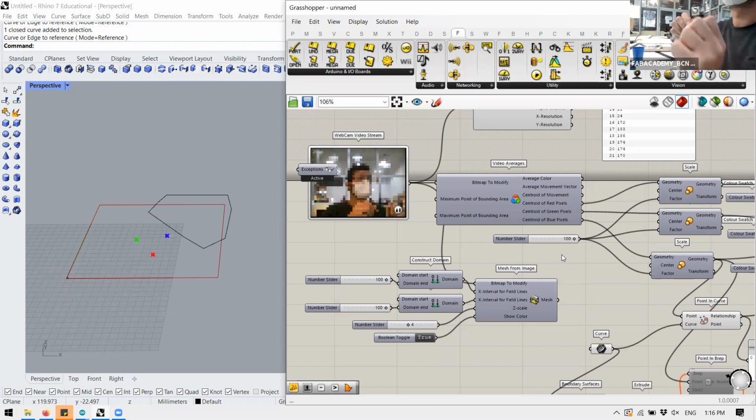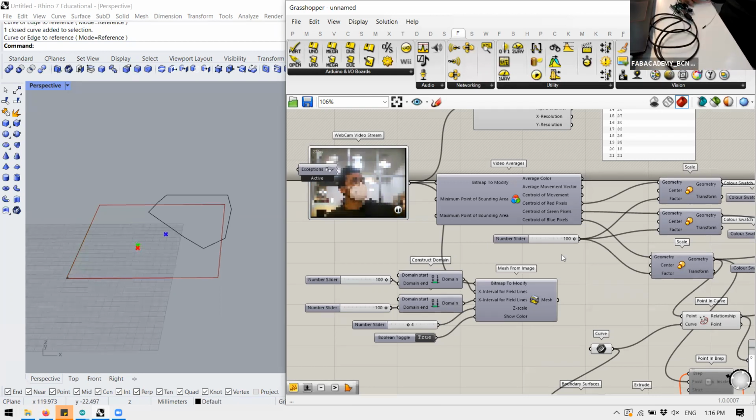Okay. So actually, this guy is a joystick. These joysticks, what are they? It's potentiometers. Two potentiometers, one for the X and one for the Y. And they have a switch button also in the middle. So let's connect this guy into the Arduino. I will disconnect the servos and also connect the buttons. Ground with ground. 5 volts.